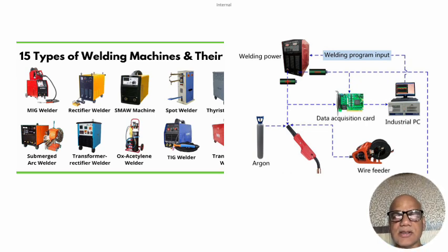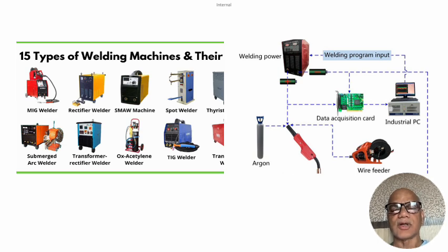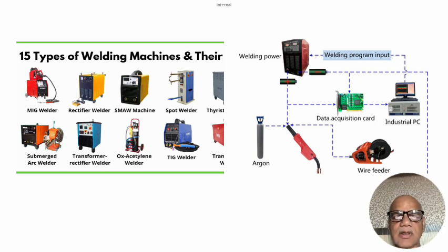It's a straightforward simple machine where you set only the current, that's the only variable you are able to adjust. Voltage is automatically set because of the transformer ratio. The rectifier or the thyristor also has a basic step down by the transformer, and subsequently it gets rectified, or the AC gets converted to DC.